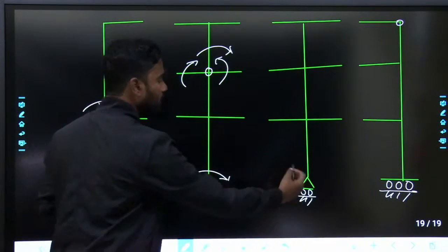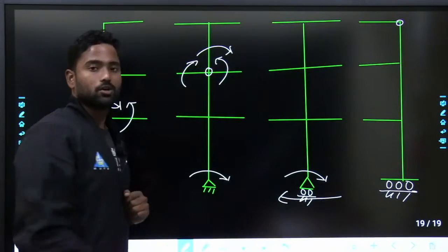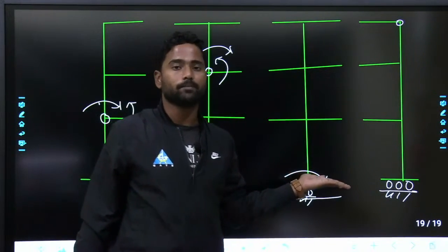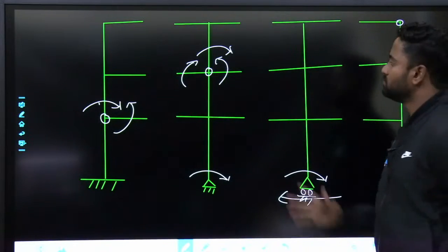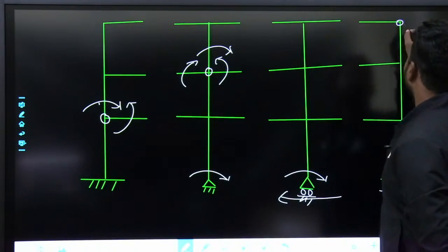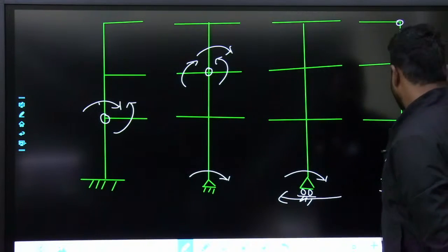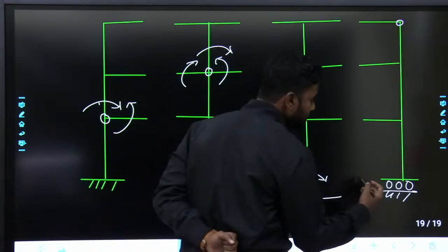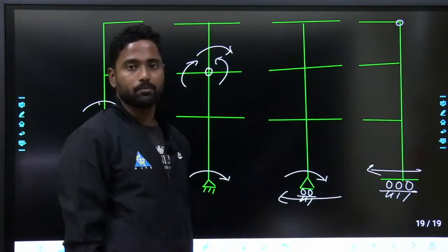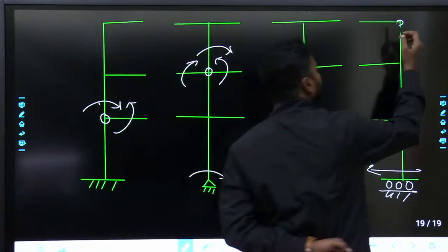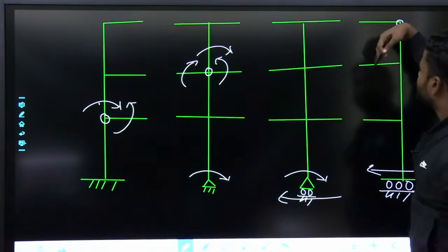And if you see here, there is a roller support, you have to add moment and the horizontal reaction so that this will be fixed. And here are there any hinges? No hinges. Leave it like that. And if I go here, here there is axial thrust release. So that means you have to add a horizontal reaction, then it will be a fixed support. Now this is hinge. Up to here it is okay, it will be straight. This will fall like this.